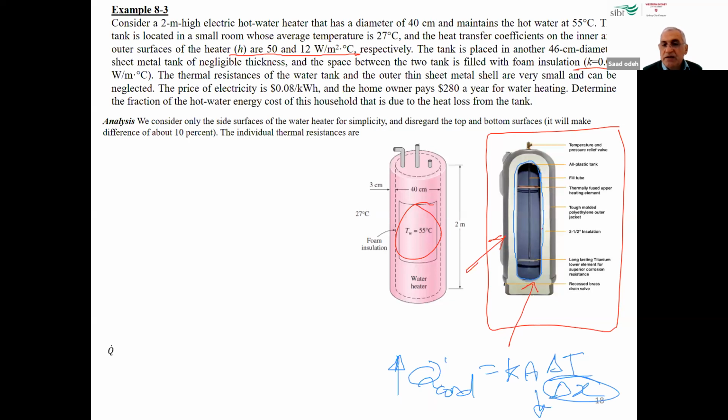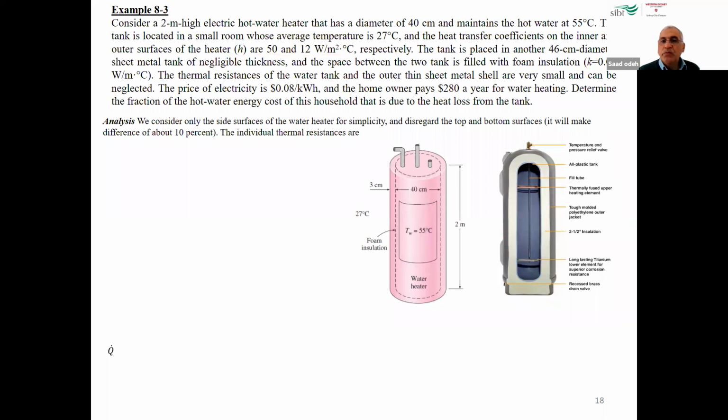That's why we are not considering the thickness here: all the heat is transferred to the insulation from the tank. So we're going to eliminate the heat transfer by conduction through the tank sheet or metal shell.